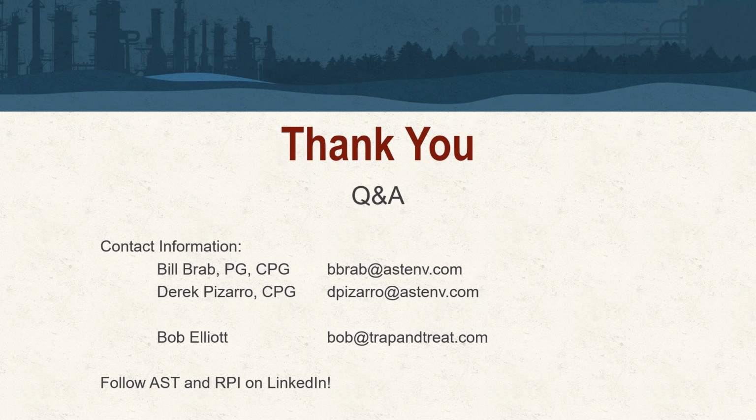Great. Similar question. How do we typically assess radius of influence in a fractured bedrock setting? Does that estimate change based on bedrock, fracture network, or other variables? And how do you estimate that at the outset? It's a good question. The majority of our distribution verification is by the use of transducers and monitoring the surrounding network as we're working. Part of this comes down to the RDC itself that we talked about last week and briefly mentioned during this presentation. Prior to putting anything in the ground, we want to get a handle on what reach we can achieve based upon a particular borehole, and take that data and modify it as needed based on what we see.